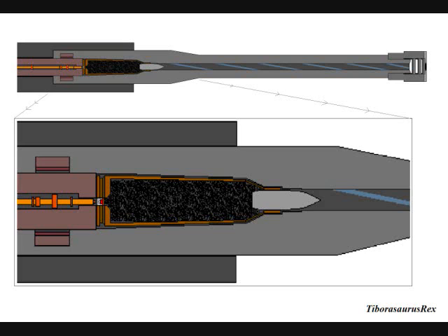So different brands of rifles will have different chamber dimensions. Most guys, for target shooting purposes who are looking for maximum accuracy, prefer chambers on the tight side. And that means that you're going to have less wiggle room between your brass case and the walls of the chamber. How that plays out is obvious, really, if you think about it, with your harmonic and vibratory nature. If your cartridge is mated up the same exact way every time, if it's tight, it only has one spot to go, right? So every time it shoots, it's going to produce a real similar harmonic wave originating from the chamber there.